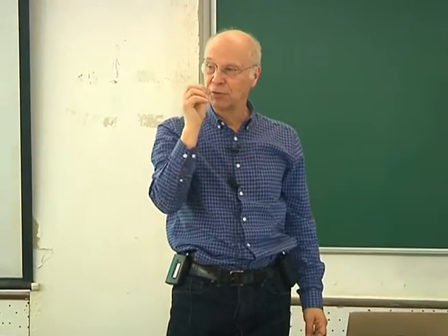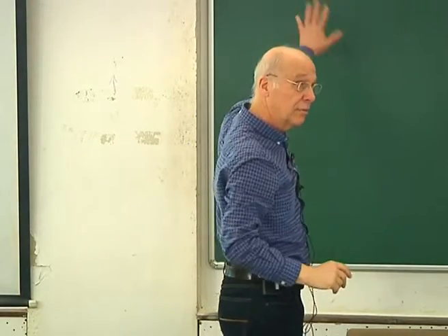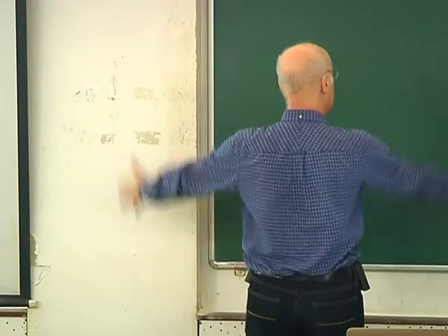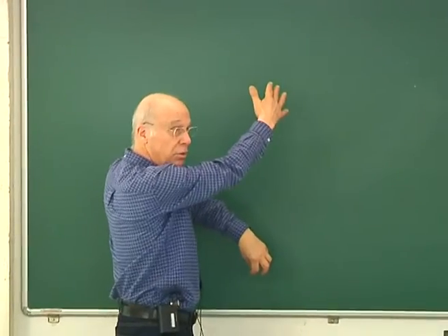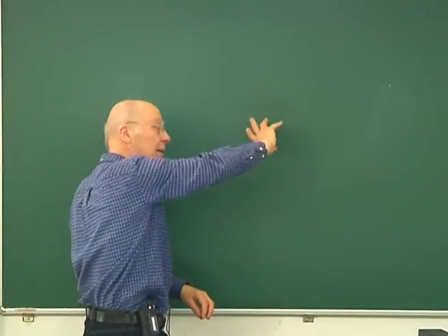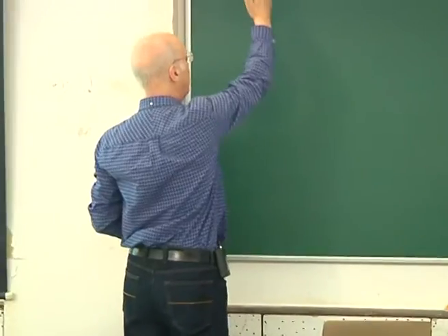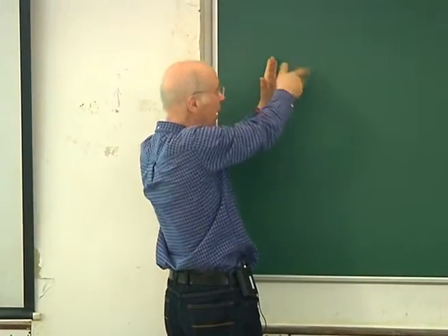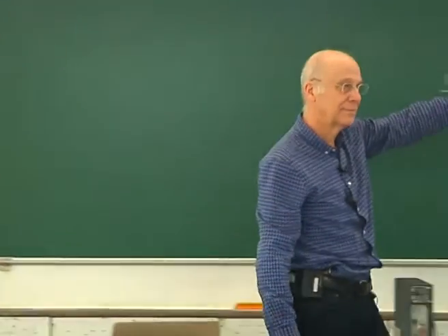So you've got negative vorticity along the top because the boundary is going faster than the flow. On the sides, however, you've got flow coming down and the boundary not, so you've got vorticity this way, which is positive. And going up here, you've got flow that way, no flow there, so you've got, again, positive vorticity. And that's what the plot is.